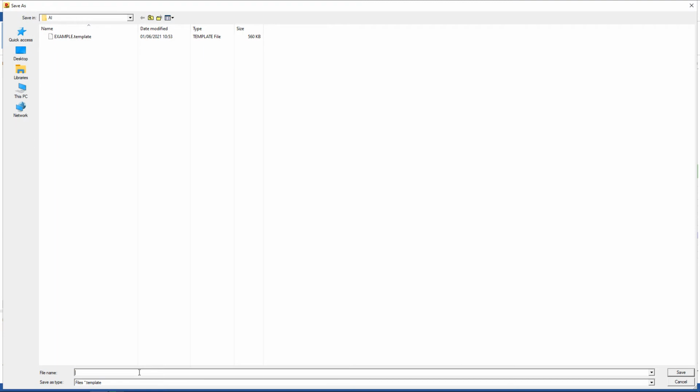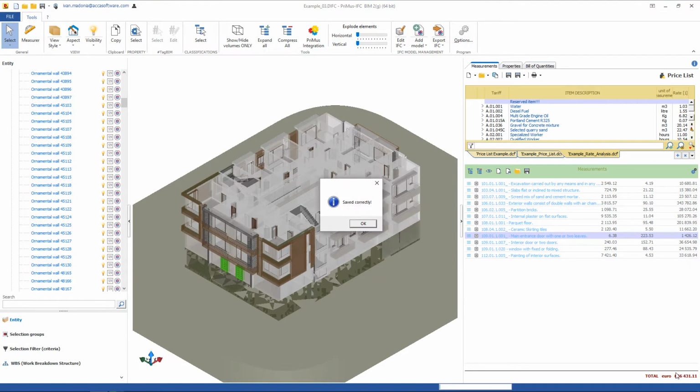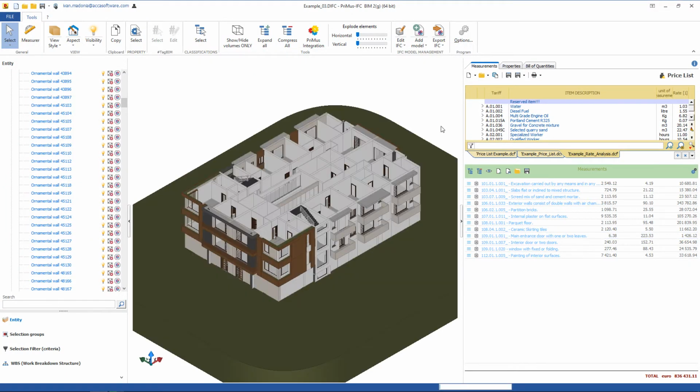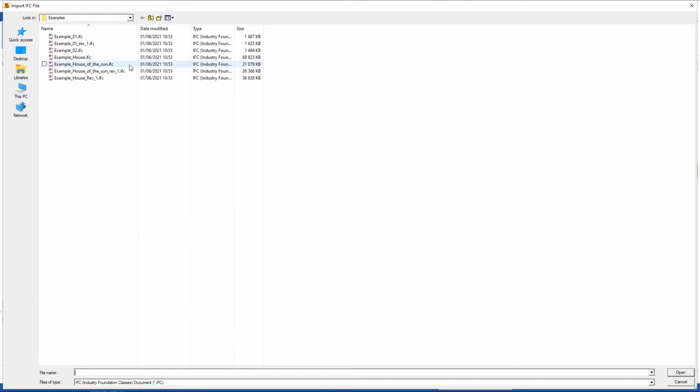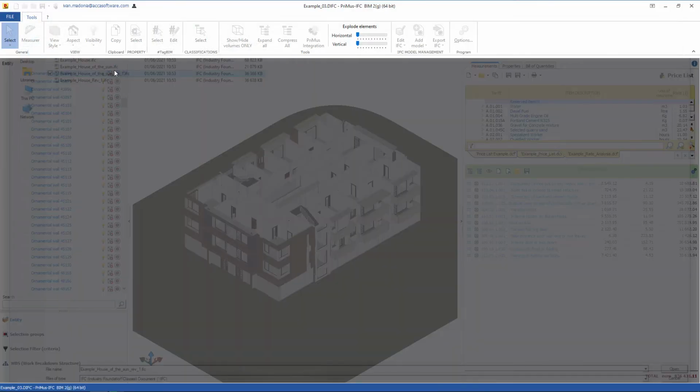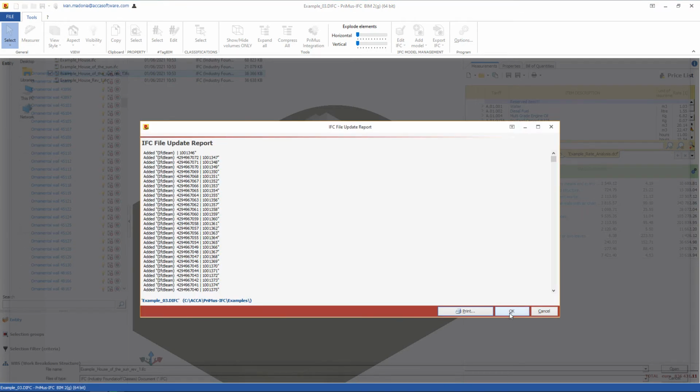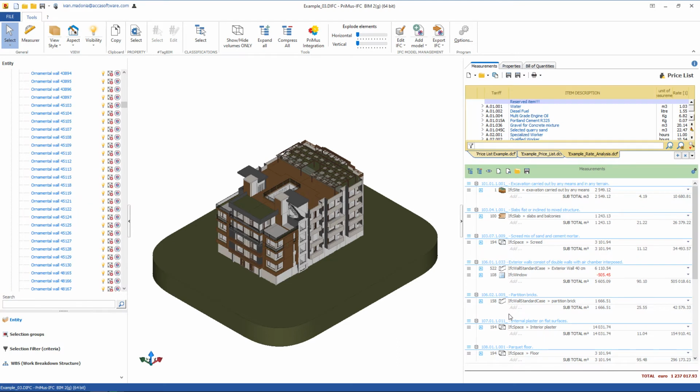But what if the entities used in the quantity takeoff only represent part of the entire building? If the original architectural model has undergone an evolution, or has simply been finalized compared to the first project, we have to upload the new available model. By carrying out this operation with all the cost estimate BOQs models already within the project, the verification of a correspondence between the selection characteristic present within them and the characteristic of the entities of the updated model will continue automatically. If they correspond, we can obtain an updated cost estimates BOQs.